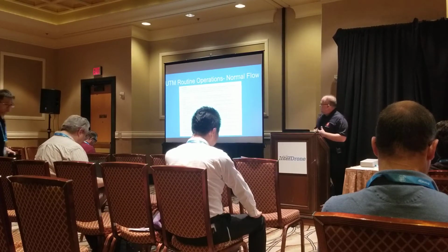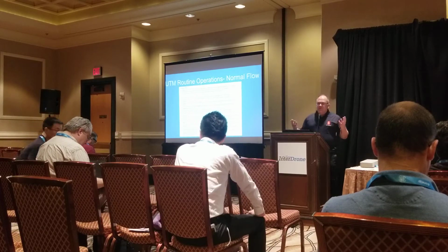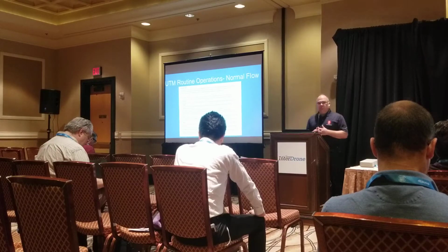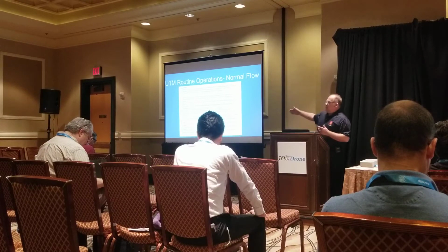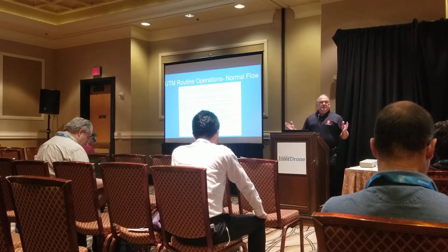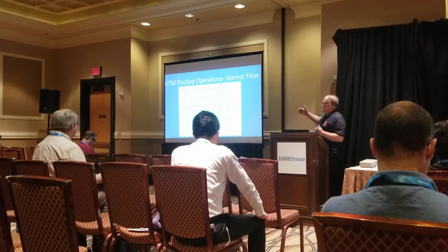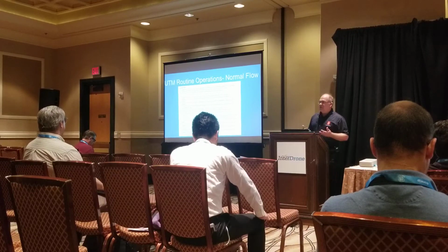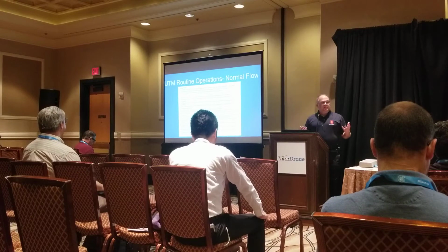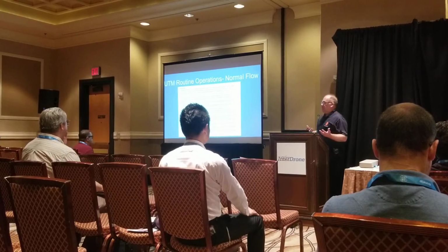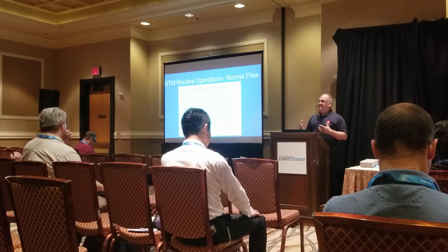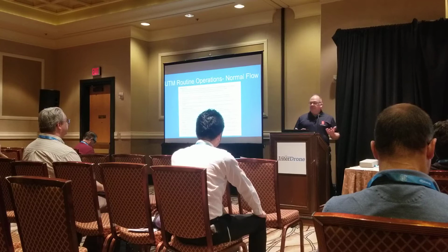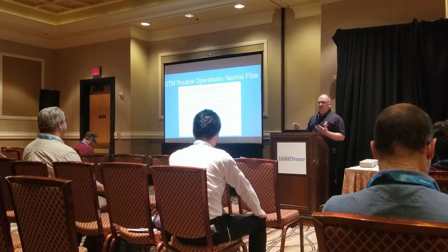From there, the recognized airspace management picture, RAMP, so it's also a nice acronym. I considered recognized UTM picture, but RUMP didn't work quite as well. But the RAMP is then used by the UTM operator to monitor the condition of the airspace. He's going to identify some non-compliances. He's then going to interact with the UAV systems and direct them to take some corrective action. They're going to confirm that they're taking corrective action. He's going to confirm that it is sufficient to address the non-compliance. Then he goes back into monitoring mode. And that's pretty much the end of the routine operations.